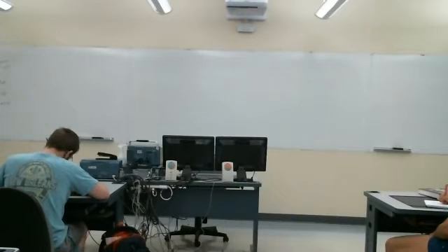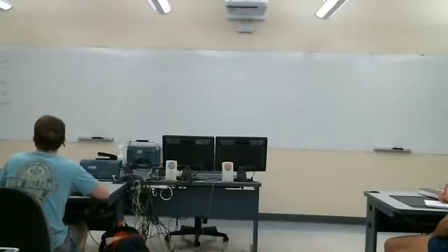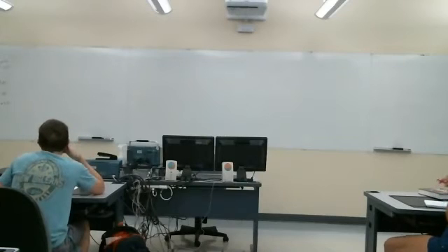What that means from a system standpoint is, if we've got a system with impulse response h of t and feed it x of t, we get y of t. Well, if you build another system whose impulse response was this first input and fed it h of t, you get the same output.